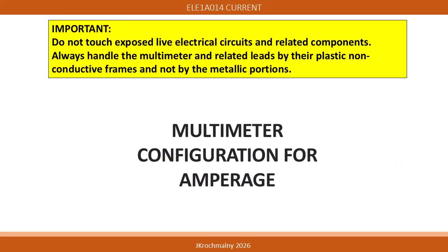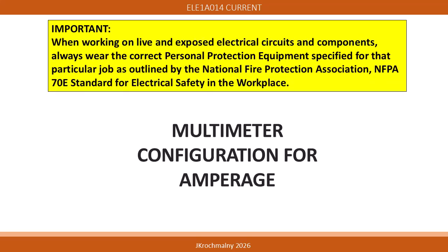Do not touch exposed live electrical circuits and related components. When utilizing electrical multimeters and other electrical test instruments, always handle the multimeter and related leads by their plastic non-conductive frames and not by the metallic portions. Utilizing multimeters and other electrical test instruments needs to be performed while wearing the correct personal protection equipment and observing the safe protocols as referenced in the National Fire Protection Association NFPA 70E standard for electrical safety in the workplace.